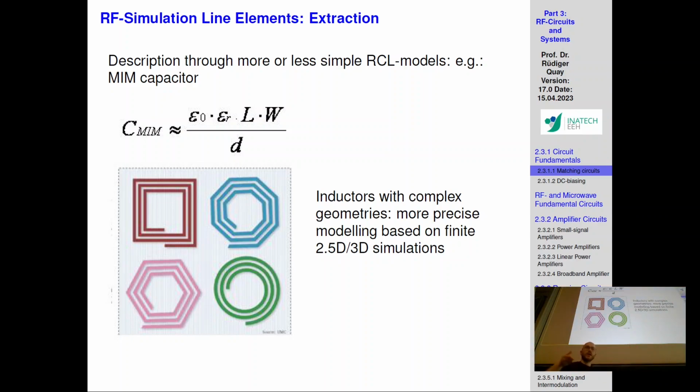Having a higher inductance means that your large signal wave, your DC wave, will not see any problem with it. It will see loss, but just some millivolts. But your small signal will see a very high impedance. In the sense of frequency, operating frequency. At the higher frequencies, this will be an open for RF, whereas for DC it will be a short. So not a short, but it will be a normal line. So I have a certain impedance.